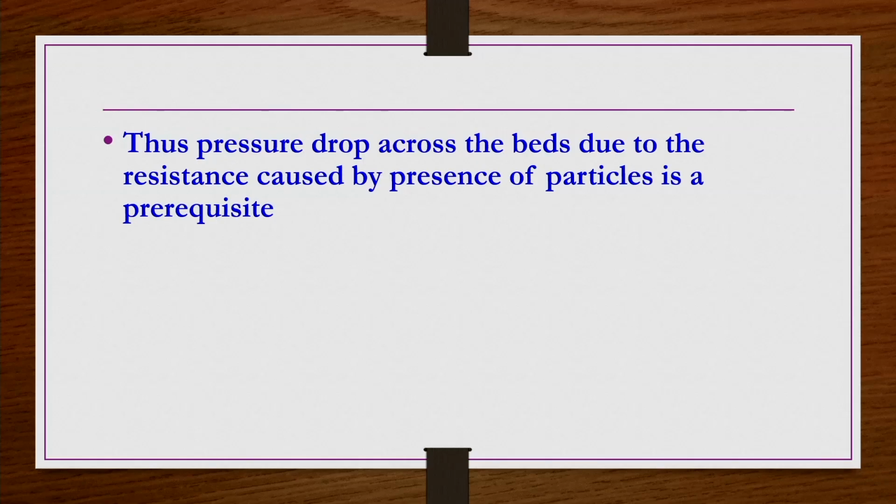What we understand is that the pressure drop across the bed due to the resistance caused by the presence of particles is a prerequisite. The fluid is flowing through a packed bed, and when it flows through the bed, it receives so much resistance because of the particles used for packing the column, which form a packed bed, right. So, these particles offer a huge amount of resistance in general. That is going to be very important.